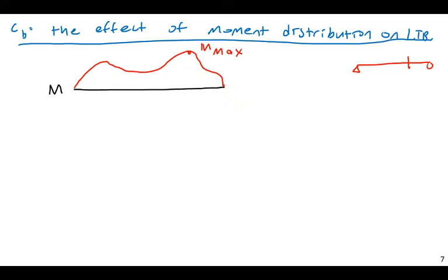But when we're dealing with buckling, that is more of a function of length. So you can get buckling without ever reaching the maximum moment. In order to have buckling, you need to have moment all the way along the beam or spread over a long length of the beam. You don't get buckling when one particular location has moment on it. Instead, you get buckling when you have a great deal of moment distributed over a large range of the beam.